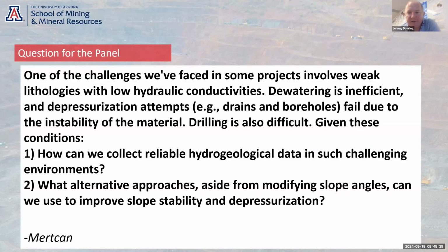But looking for the sources of recharge and trying to cut off sources of recharge is also very important. And if it's a high rainfall environment, having really good surface water management on the mine benches and above the crest to try and route surface water flows away from the weak materials is always really important. And if there are other sources of recharge into the slopes, into those weaker rock domains, then identifying what those are and trying to cut them off to minimize the amount of recharge that gets into that weaker material is always very important.